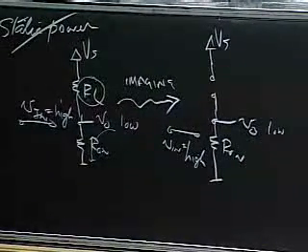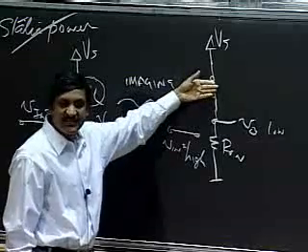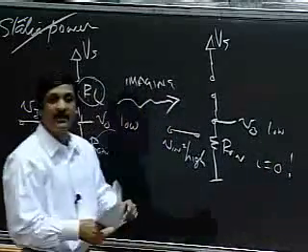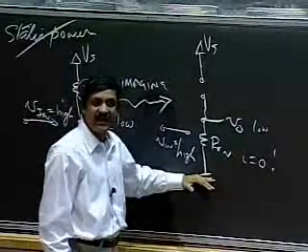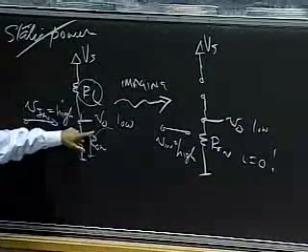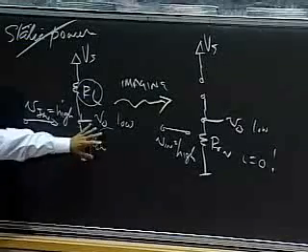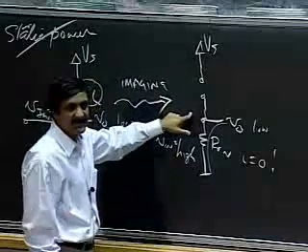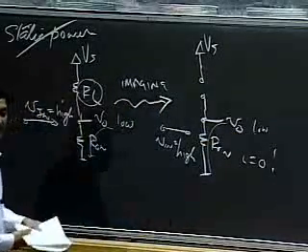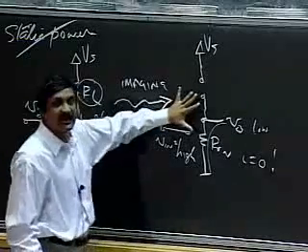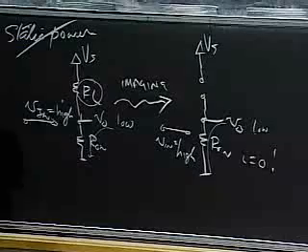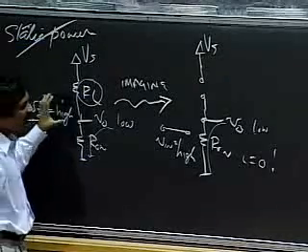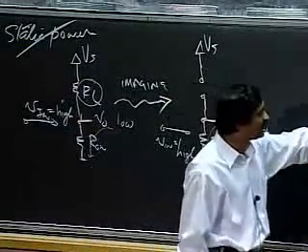I get many benefits by doing this. One benefit is that I've opened the switch here, so I don't have any standby current. The standby current is 0. Second benefit is that my output gets dragged down to ground. Out here, my output was Vs multiplied by R on divided by the sum of these two. Out here, I have a direct connection to ground and nothing to the power supply, Vs, and therefore I have a nice solid low. So the question is, can I get this situation? That is the key insight. Imagine that somehow when this was high, I could get this to open up, much like when this was low, I got this to open up.